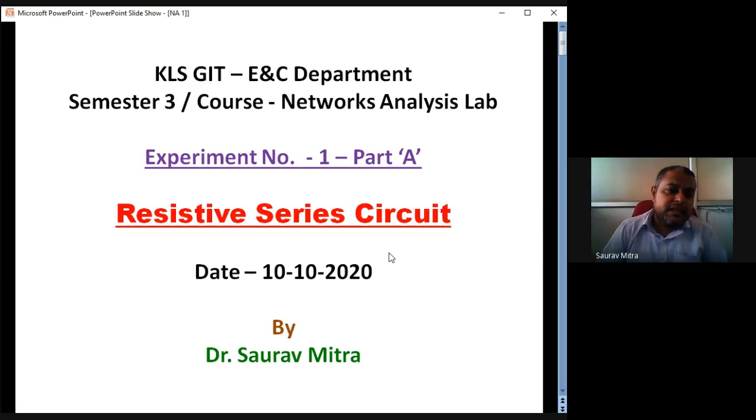So this lesson is very easy: connect the voltmeter in parallel, connect the ohm meter in parallel, and connect the ammeter in series. While solving numericals, we are not connecting the voltmeter, ohm meter and all; we are finding all those values. But while doing experiments, students generally get confused about how to connect in series and how to connect in parallel. That is the main caution, and how to actually understand what to connect in series, we will discuss a little bit today.